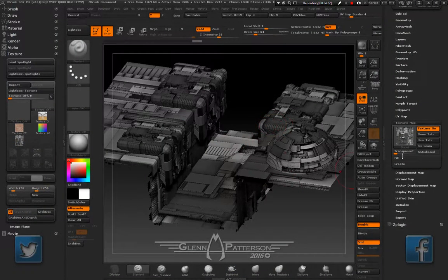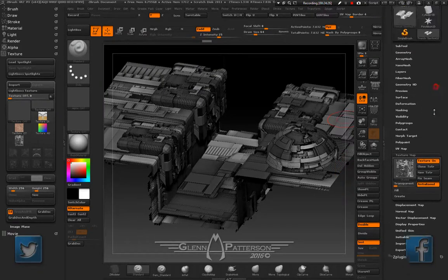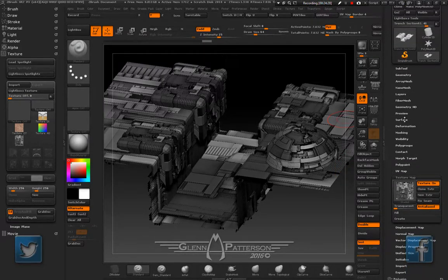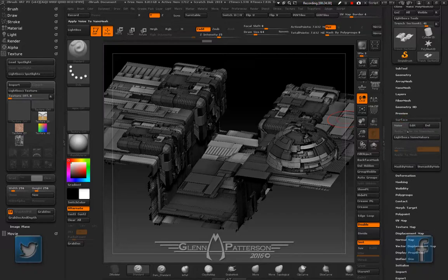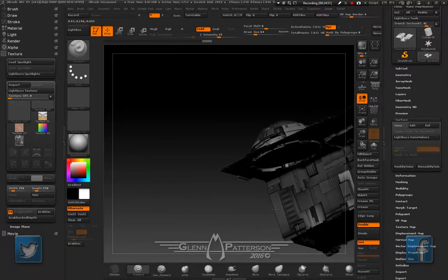Discard. And real quick, the only reason that I made sure the surface was at 1 to 1 scale was if you do an alpha scale and adjust it, your shaded texture map won't line up to the model. It won't jive with it. It won't notice the difference in scale. It's just going off the original. So just something to keep in mind if you wanted to do that trick.